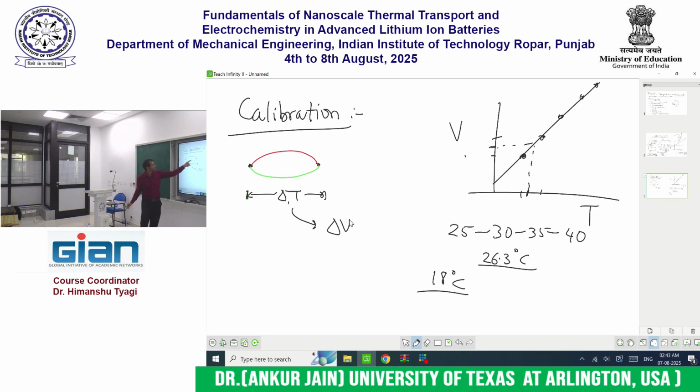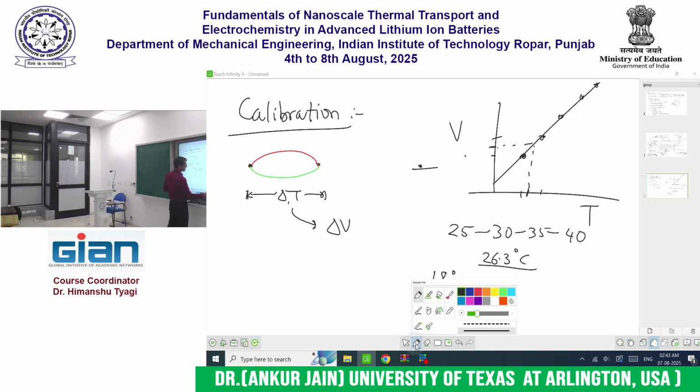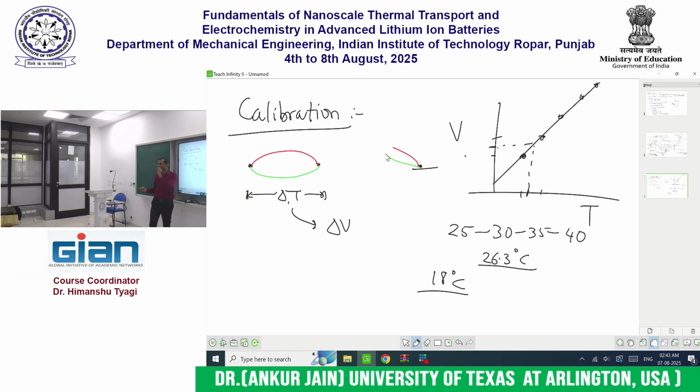But now if this thing begins to heat up, you've taken this thermocouple and you've attached it, one end of the thermocouple is attached to some surface. The 2 metal wires are coming out. As this thermocouple bead gets hotter and hotter, a potential difference is produced.